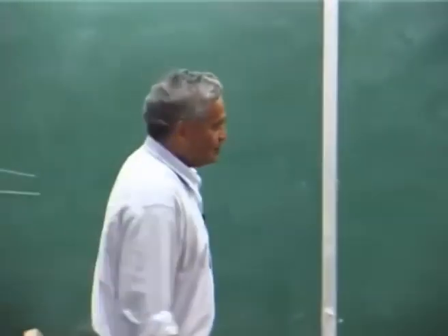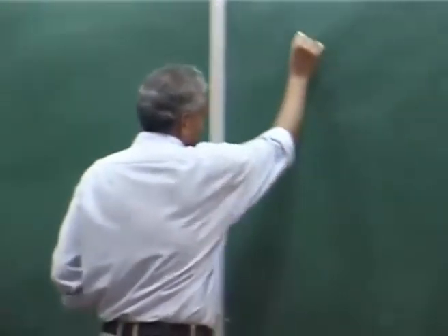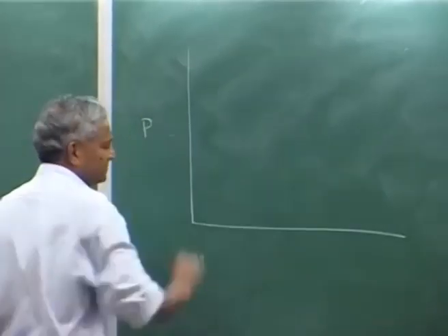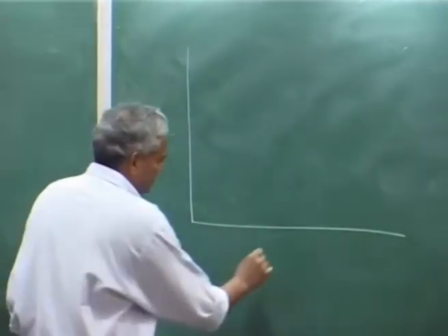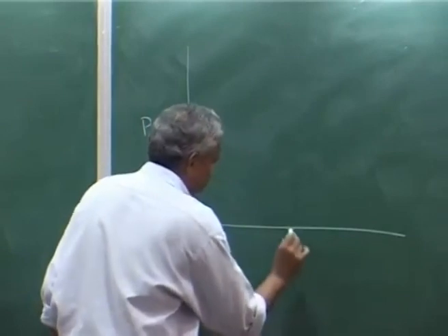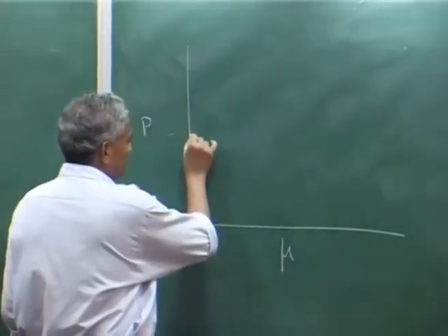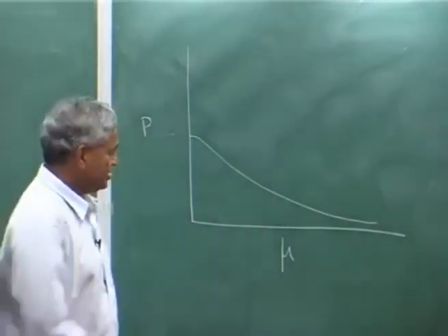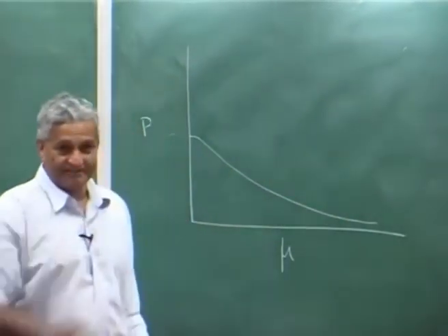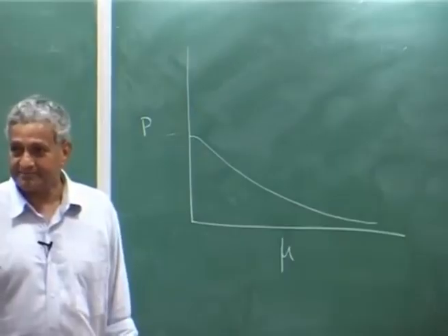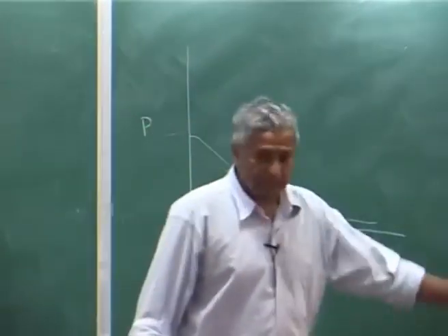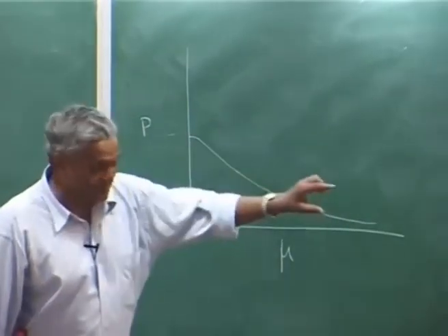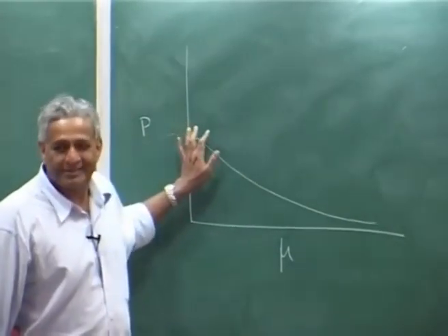Now if you look at the power graph, this is the rotor power, this is forward speed, induced power will go like this, because induced will keep on decreasing with forward speed. I am taking mu starting from hover, even though that expression is not valid at hover, okay.